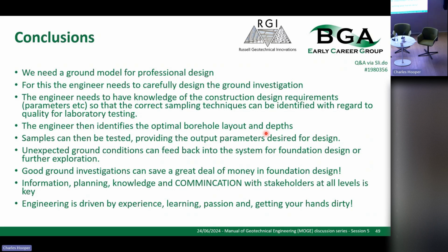Unexpected ground conditions can feed back into the system for foundation design or further exploration. We've come across very unexpected things and parameters in materials, I can assure you, but it's the honesty and the integrity that we are telling the client there's something not right. If we find something with a sample that isn't doing something that's expected, the first thing that we do is calibrate everything and check. If something appears to be not so stiff or doesn't have the strength that we would expect, it's definitely a hands up thing.